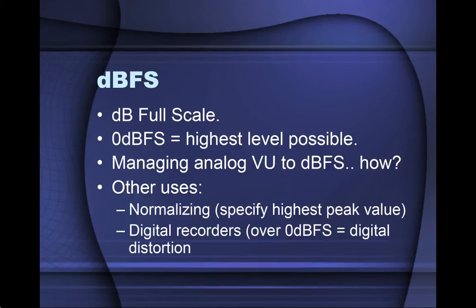Well, it's the same way here. You want to try and get as close to 0 dBFS as possible to maximize your signals, but if you go over, you end up getting some digital distortion, or you end up kicking in the fail-safe compressors or limiters, and it ends up affecting your sound that way. So it's one of those things where you want to try and get as close as possible without going over. So all of your values are typically going to be minus dBFS, with 0 dBFS being the maximum.